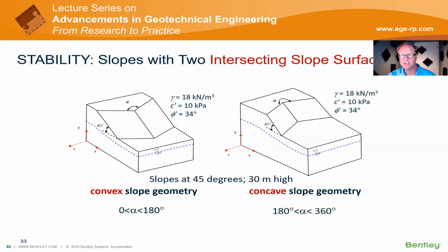Previously, I should mention that when we've designed slopes with factor of safety, we have just assumed that we won't do it in 3D, we use 2D because I know that 2D is conservative and it helps me. But why not know what the difference is so that we can actually plan for it and design for it? That's really what 3D modeling is about: bringing your model closer to reality and eliminating some of the unknowns that we have always known are there, but we just didn't know what they were.